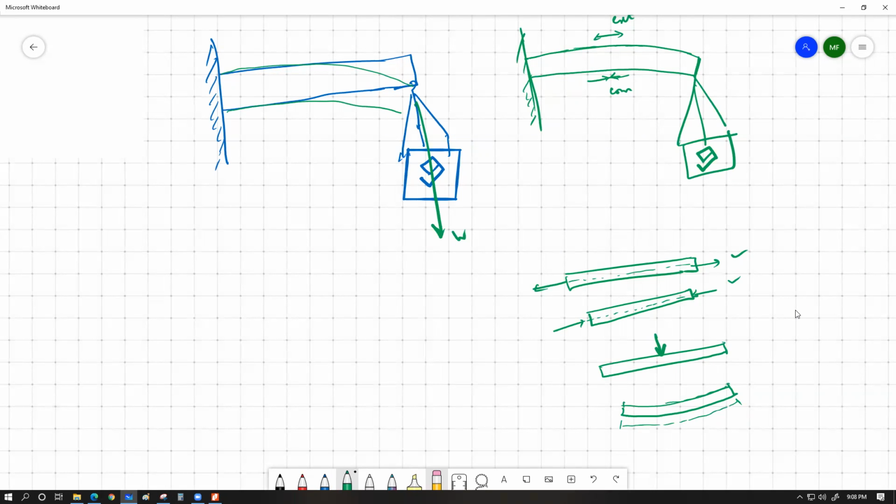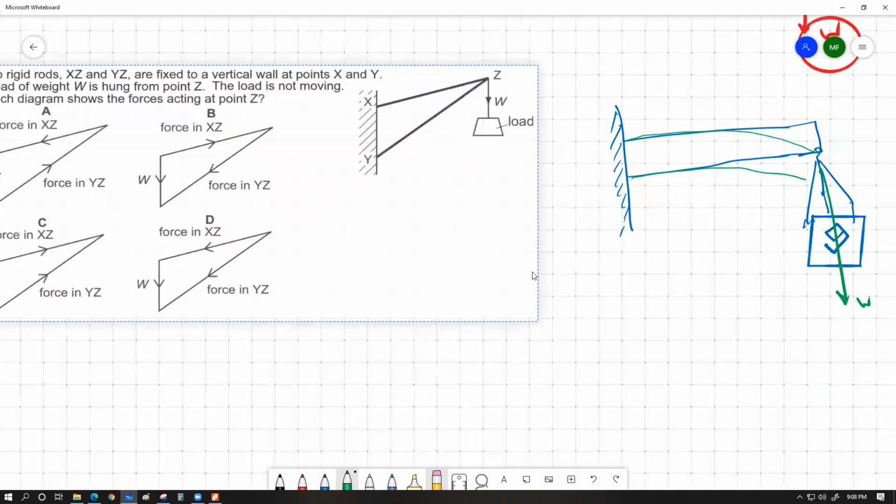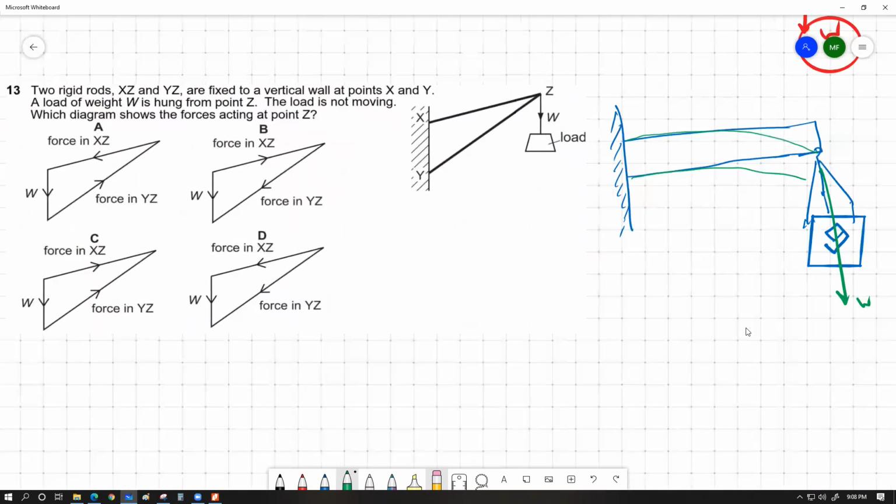Yes, sir. Now if you consider this same single image and consider this whole thing XYZ as a composite object, you should understand that whenever the load is working over here, this upper part of the bar should be in a state of tension, and the lower part over here should be in a state of compression. So that's one way to judge this whole problem. There is another way to come to the same idea, just by looking at the figure for individual lengths of the rods one at a time. Let me put it this way.